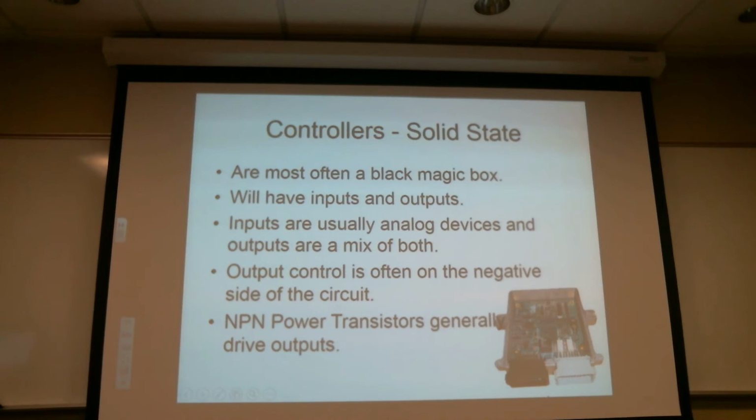The other thing, and if that's the case, it's almost always the output device is overloading the circuit. Something's wrong. The other thing that tends to fail is you tend to get broken solder joints, and that's heat and vibration does that. If that occurs, again, the fix is going to be to replace the unit. You're still going to want to make sure that none of your devices are overloading the circuit.